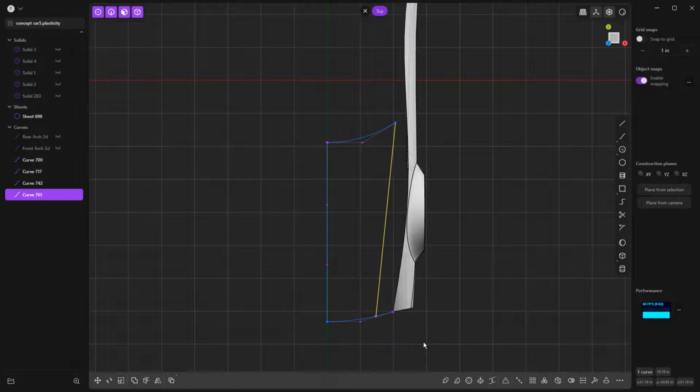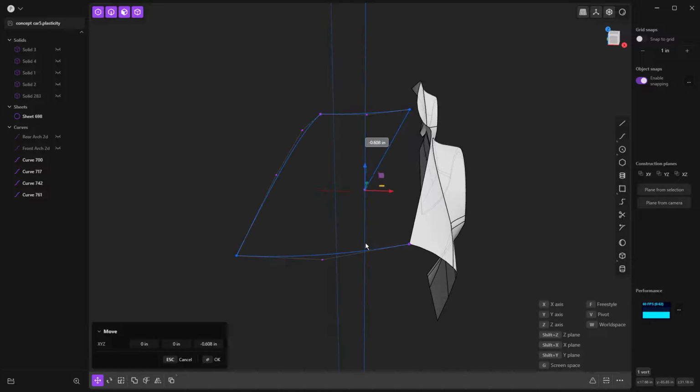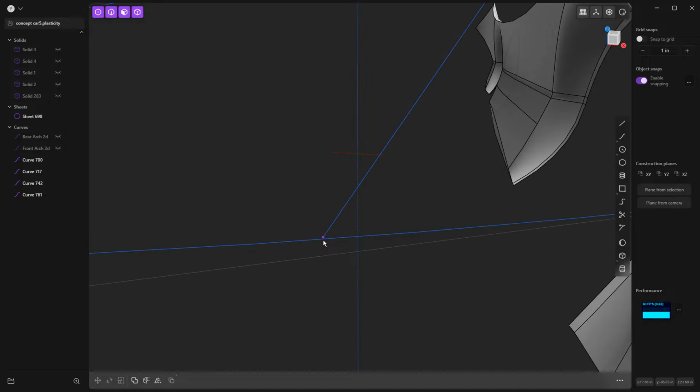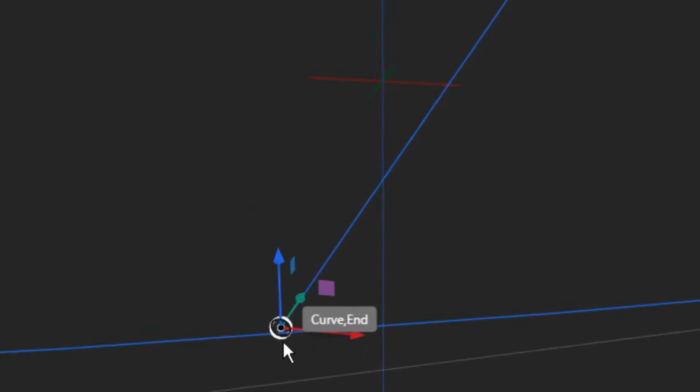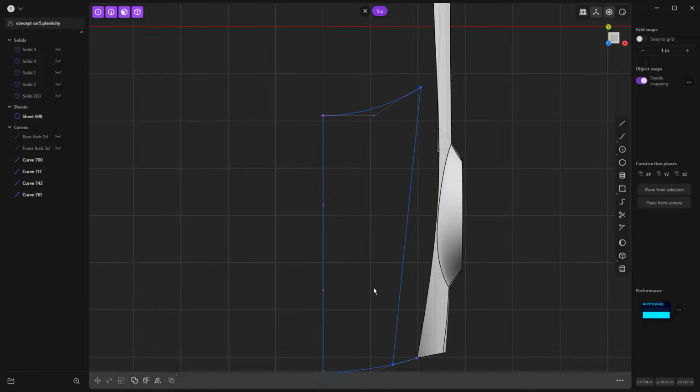Now, again, keep in mind that endpoint, because we were looking top down, isn't actually going to be connected. So we need to do GZ and hold down Control to make it snap. If this endpoint doesn't turn blue, then it didn't actually snap. So GG, hold down Control and make sure the tooltip next to the cursor says curve, and then that should turn blue.